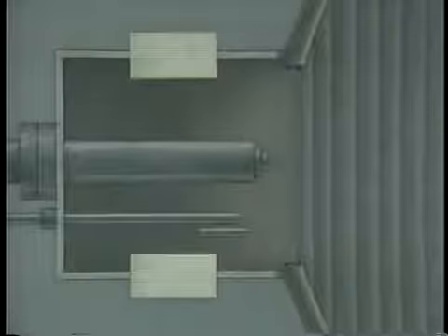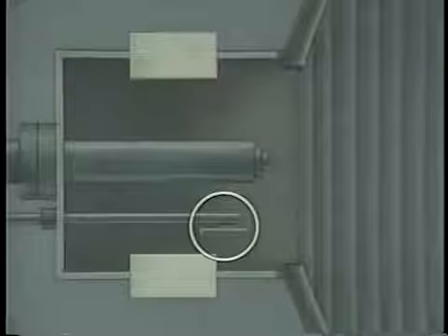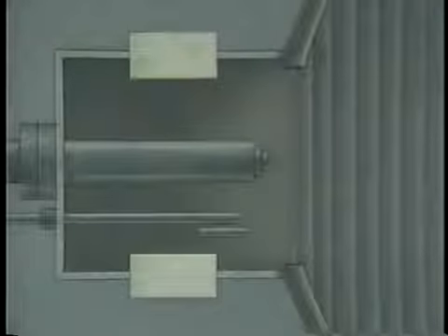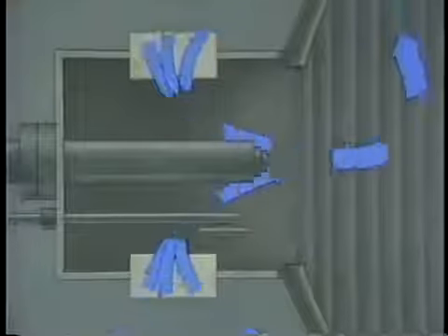Now, that's the way it's supposed to work. However, boiler explosions occur during unusual conditions. Let's suppose that the igniter malfunctions and does not spark as it is supposed to. We'll use the same illustration to see how an explosion might occur. The operator turns the controller to start the igniter sparking. However, in this case, the igniter is slow to respond and doesn't spark right away. The operator next establishes airflow to the burner port and then starts fuel flow. The igniter still doesn't spark.